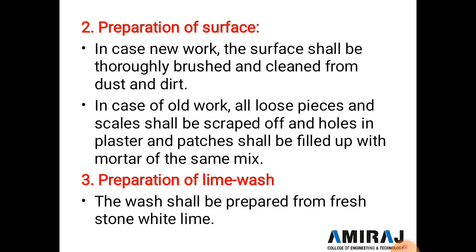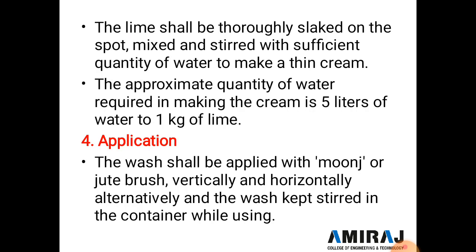And the third specification for whitewashing is preparation of lime wash. The wash shall be prepared from fresh stone lime, and the lime shall be thoroughly slaked on the spot, mixed and stirred with a sufficient quantity of water to make a thin cream. The approximate quantity of water required for making the cream is 5 liters of water to 1 kg of lime.